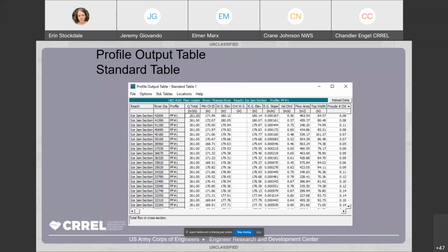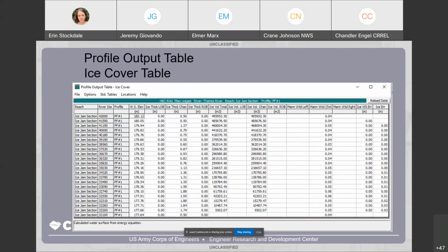And then finally, we've got some tabular output. There's lots of hydraulic variables that RAS calculates for each time step. We've got flow rate, water surface elevations, and velocities and stuff. There's a lot more other stuff you can dig into if you're interested. And so you can export these to Excel and make some plots or whatever if you wanted to, or like I said, they're exported to a DSS database format, and that allows them to be used directly in other HEC applications, or you can pull them into some other process using a script or something like that. It's a pretty handy data format.